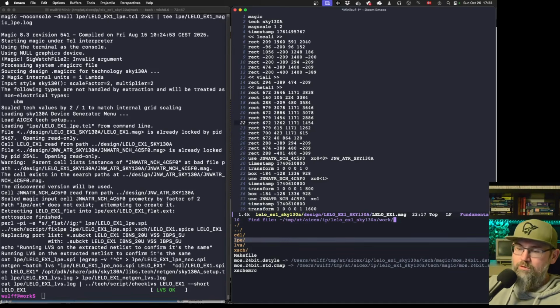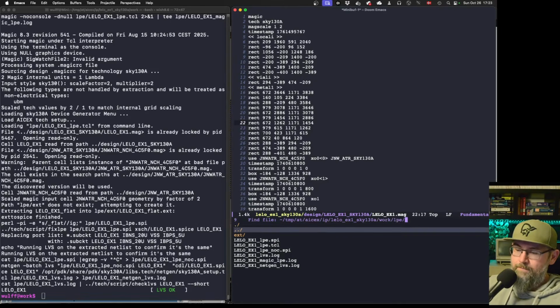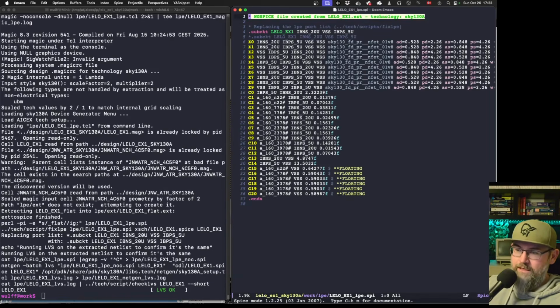In this case, for almost all the designs that we're doing in Skywater, not all the designs, but it's most common to extract only the capacitances. For most designs, like low frequency designs, it is sufficient to have the capacitances. Sometimes we do include the parasitic resistance also, especially for power nets and things like that. So things that consume a lot of current, you need to extract RC. And then for really high frequency stuff, you may even need to extract inductances also. And I promise you, those type of simulations take forever to run.